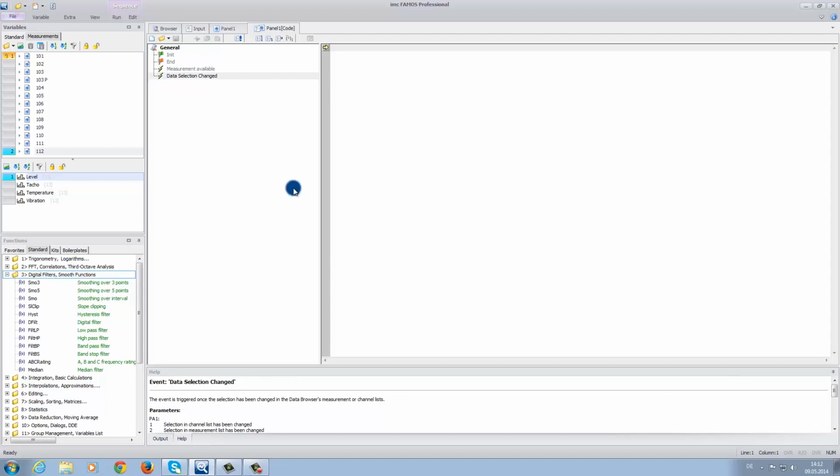Now what I would like to do is to calculate the amplitude spectra from the vibration data set. In order to do this, the program needs to know what data set to look at for the corresponding change. I will do this by entering the function to correspond to the marked data set. First, I will begin by changing our vibration data set to the turquoise-colored 1. Then, in the upper data area, I will click next to the folder 101 to cancel it as the reference measurement, as it was in the previous tutorial.